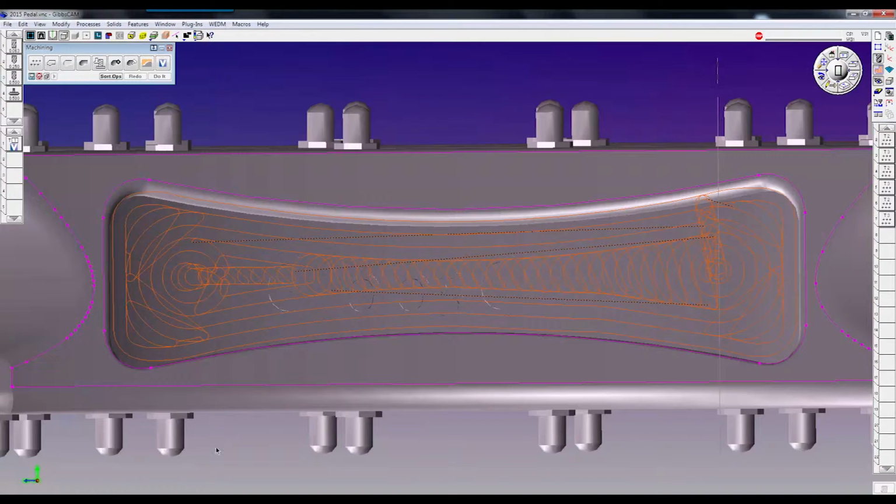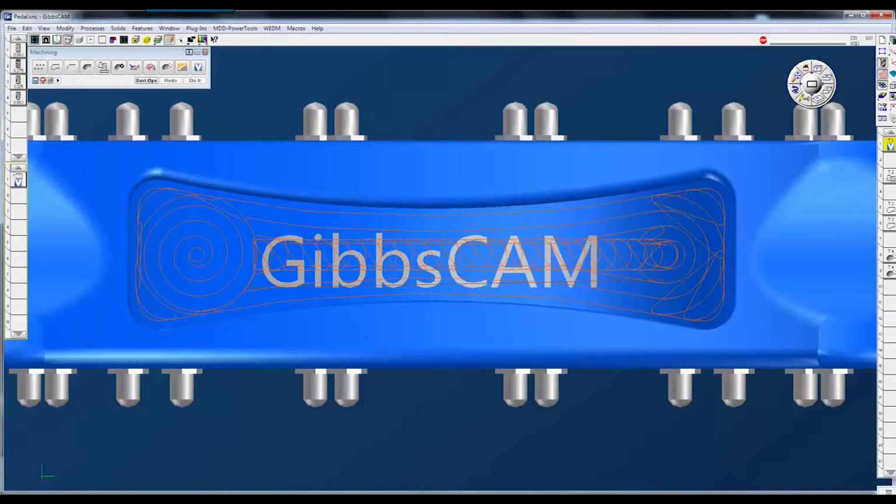So if we look at 2015, we can see that this is a pretty symmetrical toolpath. On the left, we have these corners, slotting that mimics what's going on in the middle here on both sides. Here's my lead in, things like that. Let's go ahead and look at 2016. In 2016, we can see that it's a lot more efficient. VoluMill wants to fit in spiral toolpaths wherever possible, which cuts down all of the back and forth stuff.